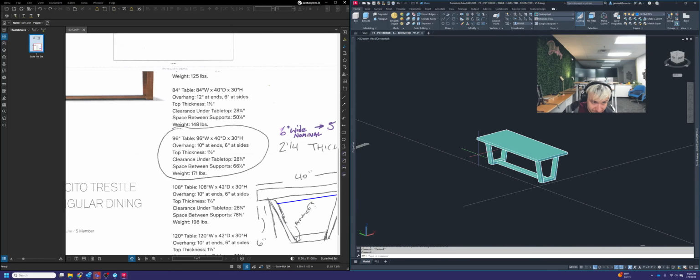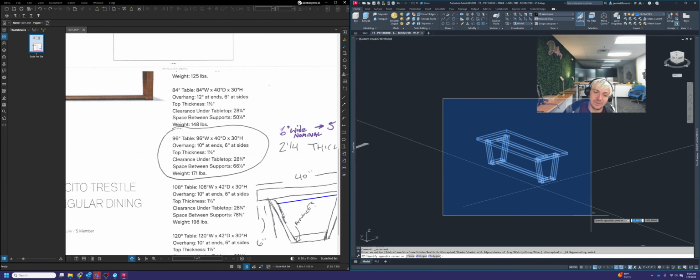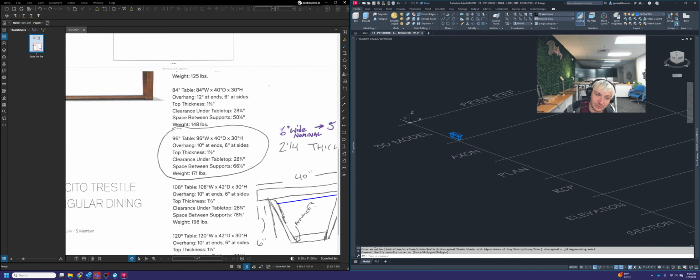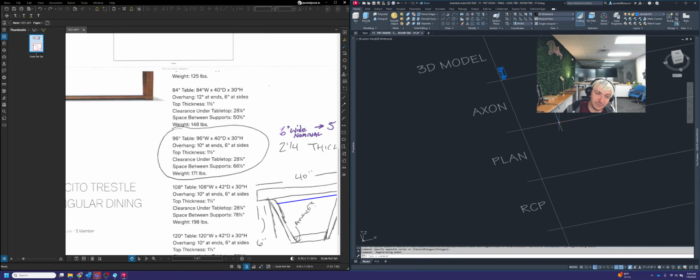It's looking really good. What we can do now is I usually will flip back to 2D wireframe for my visual style. So we're going to go back to 2D wireframe, and then we're going to start doing our flat shots. So I like to start these in the order of which I'm plotting the drawing. So just like when you plot a drawing, you always start with, if you have a model, you're going to make an axonometric view.